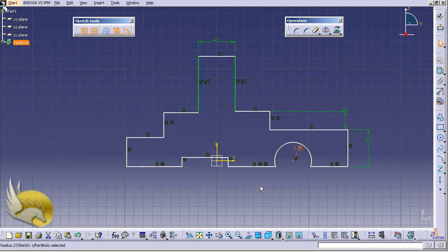Now I need to add some more constraints here. For example, I click on the constraint tool, select this vertical line here, and you can see that it adds some constraints like this. Click here, it is 10 millimeter, that's okay. And again, I want to select it by using the constraint tool and clicking on this. And this time you can see that it turns purple.